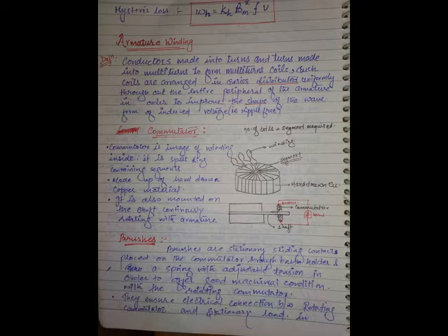If MNA shifts, think like that. MNA is not a physical axis, not a pole. Let us think imaginary axis. If MNA is not here, MNA is shifted due to some reason. What is the reason? We'll discuss. Due to some reason, if MNA shifts, what we have to do for improving commutation? Shift the brushes also. Is the point clear? For some reason, if MNA shifts, then if you want to improve commutation, brushes also need to be shifted onto MNA.